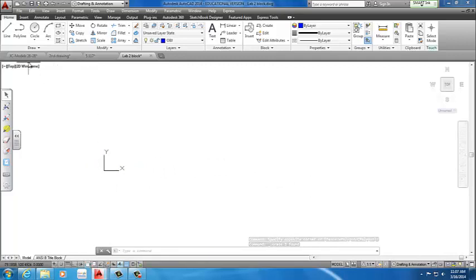If you don't see it, again, I use the line command, line 0, 0, select the origin 0, 0, or the endpoint. If you do not see that endpoint, place it somewhere, and you'll see where 0, 0 is. Right-click on your OSNAP. Make sure you have endpoint turned on. And make sure your ortho is on. At the same time, you might as well turn on midpoint.